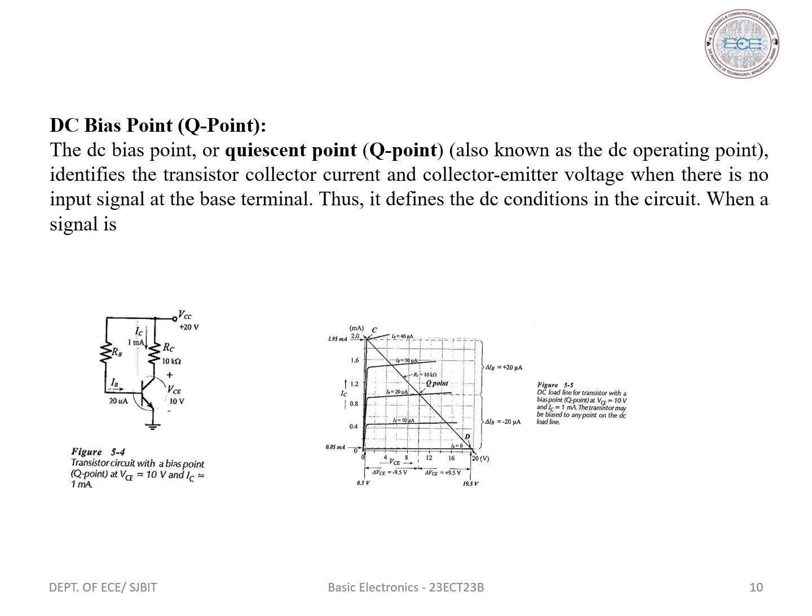If the transistor is being used for amplification purpose, then the Q point should be exactly at the center of the load line to avoid any distortions getting introduced in the amplified AC waveform.